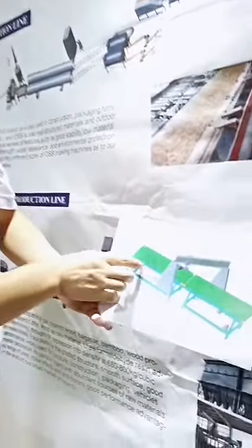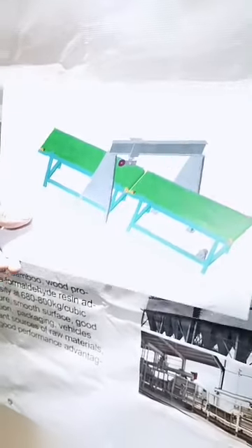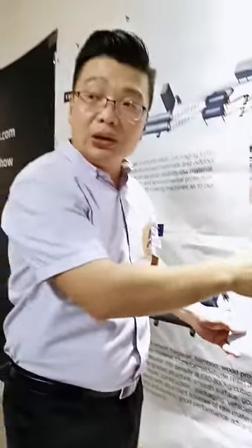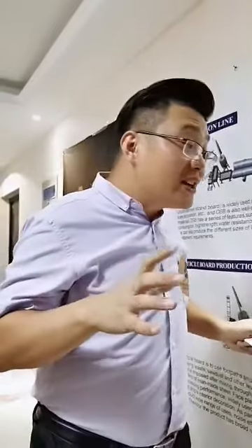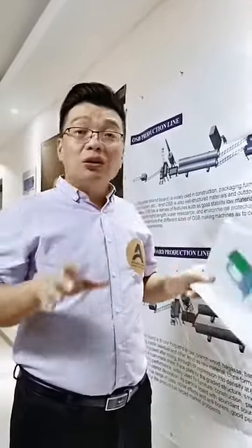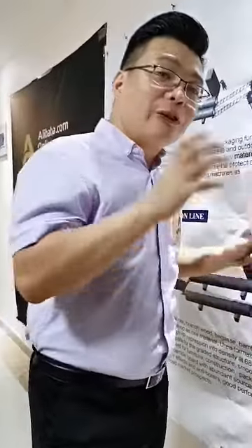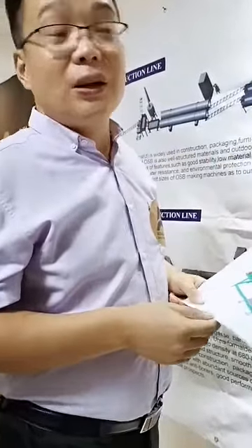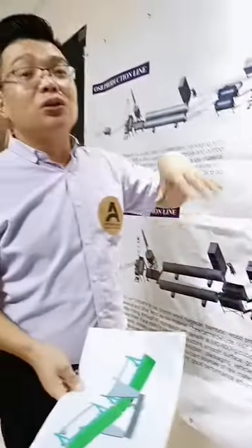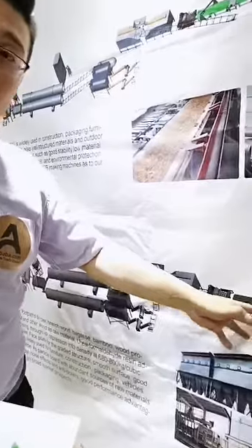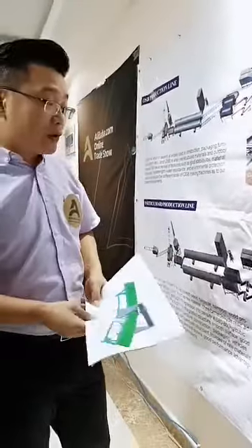It cuts according to different lengths while moving. Then after the cut, there is a weighing belt, because we always have requirements for the density of the particle board. The size is fixed, so how do we get the density? Through the weight. If the weight is not enough in the same size, then the density is not enough. So there is an electric scale here to weigh every board. If it reaches the density, fine; if not, there is an alarm, a warning, and the board is rejected and recycled to the beginning, then screwed and transferred to the raw material.